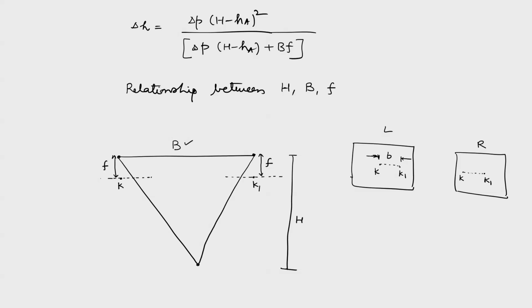Why? Because the real terrain, or the 3D topography of the terrain, has been photographed in an image with the help of focal length. So, my focal length is basically representing the flying height H. All right. So, from here you can develop some kind of triangles, and then using this triangle logic I can say that the airbase B and the image base b are basically connected, but how are they connected?